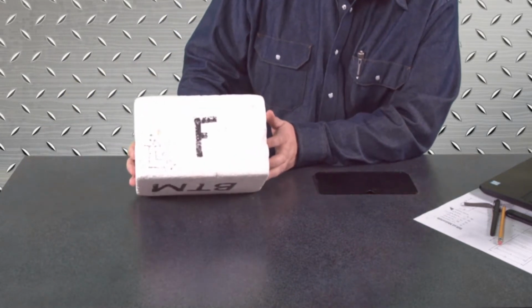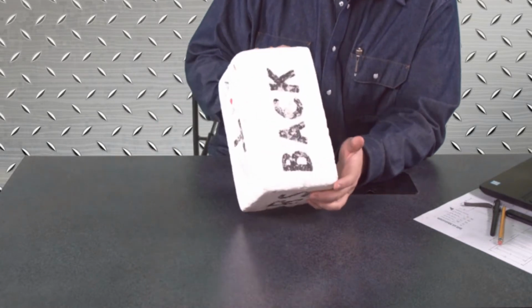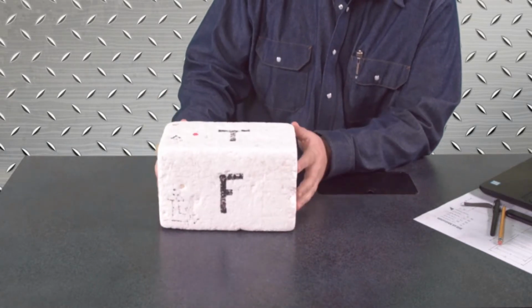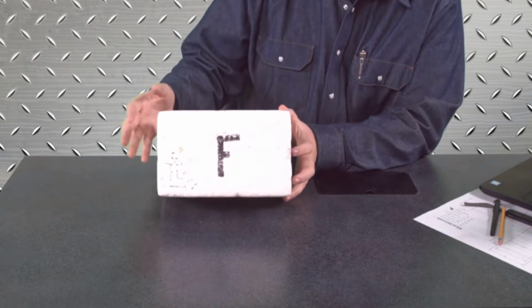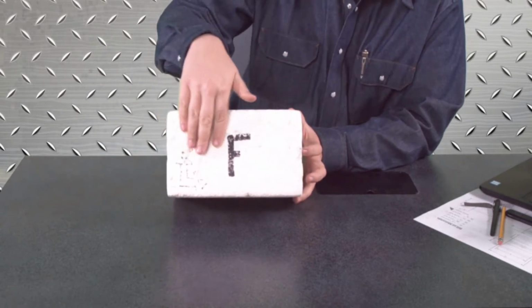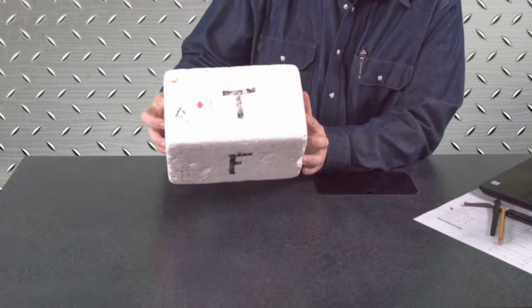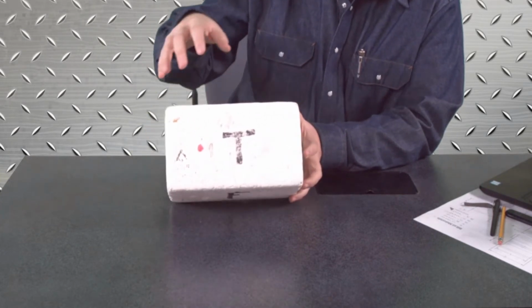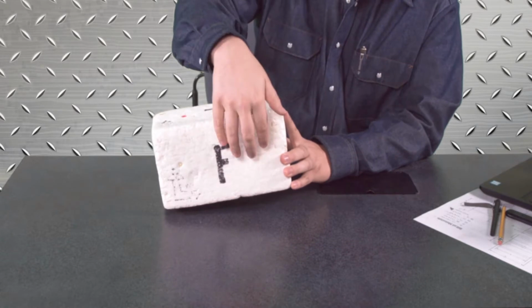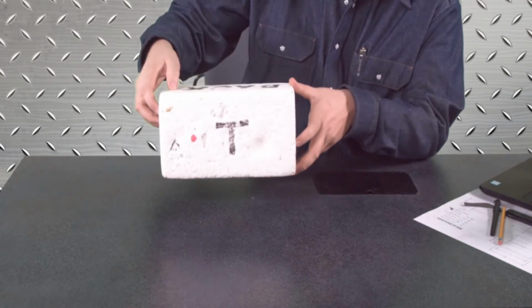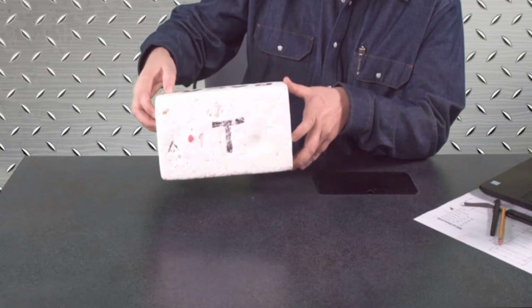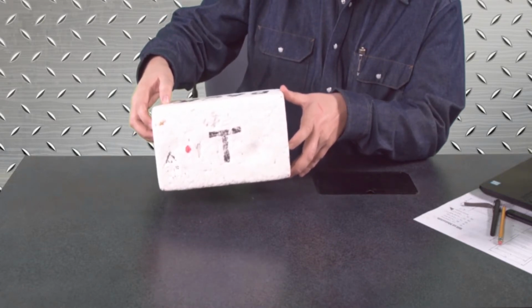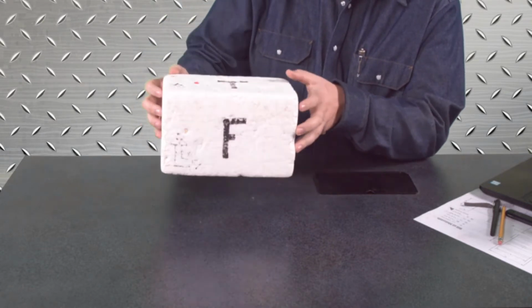So each object you can think of, this is a square three-dimensional object. We have our front, which is our F basically. So whenever you get a drawing, you'll see this front side view. You have our top, so if you were to actually take the object, here's your front, and rotate it and physically view that object from the top, that's the view that you're seeing whenever you see a top view on an orthographic projection, okay? I'm gonna rotate it back to the front.